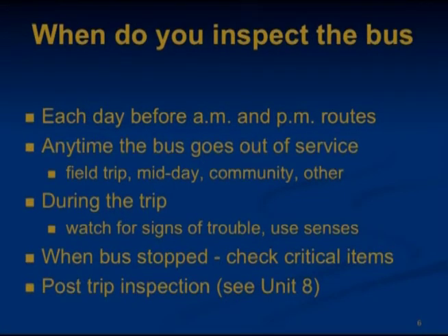You inspect the bus each day before the morning and afternoon routes or any time after the bus goes out of service. We will discuss how to do the inspection at a later time in the program. Anytime the bus goes out of service, for example a field trip, you would need to do another pre-trip. If you took a group to a football game after your afternoon route, you would perform a pre-trip before you bring the team back from the game.